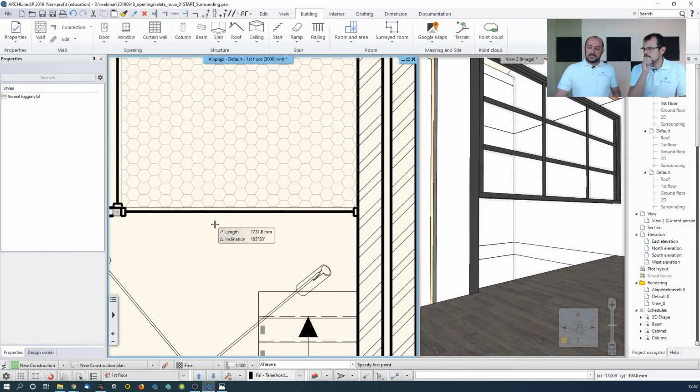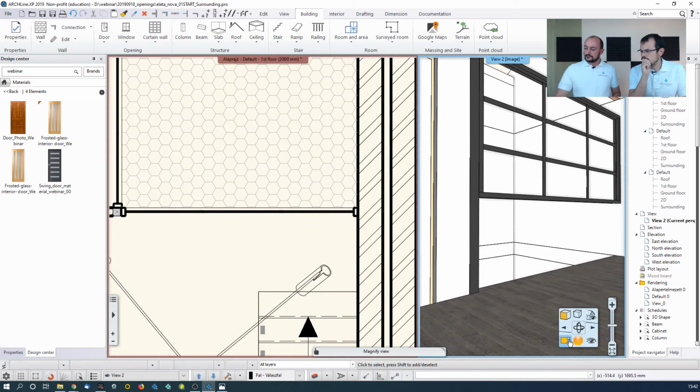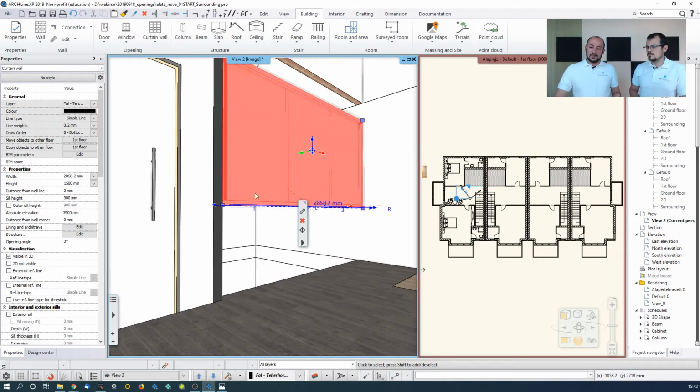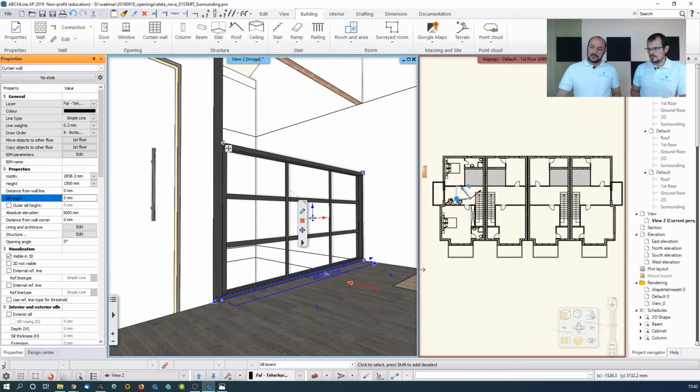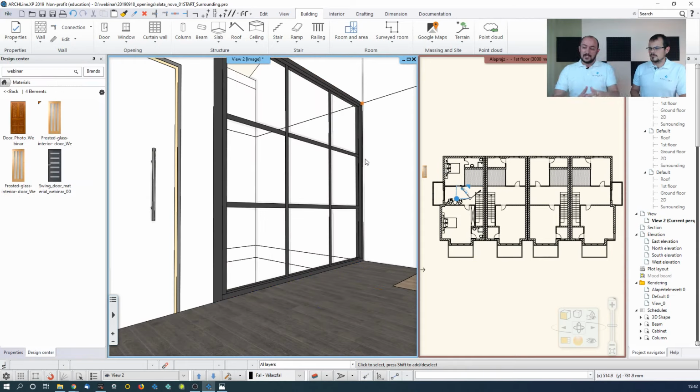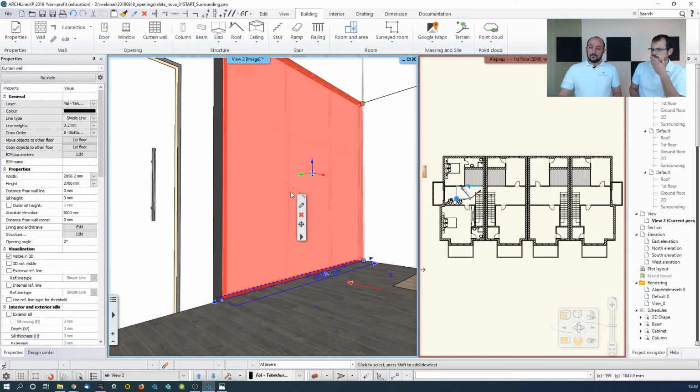Yeah, and now the 2D is correct, but the 3D perhaps needs some cleaning up. In that case, you either have the option to go here and change the sill height, for example, to 0, or you can click on any of those markers and instead of changing the height, I don't know the height now exactly, so I click here and click on change height and snap it to something that exists already there, and then I have this 3D feature appearing.